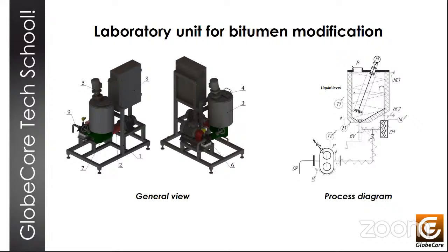The uniformity of the process of dispersion of the polymer in bitumen is ensured by constant mixing of bitumen during its circulation through that mill in position 2. So a circulating flow of bitumen is created in the pipeline system. You can see it under position 7. And the finished product is pumped out by the bitumen pump 6.